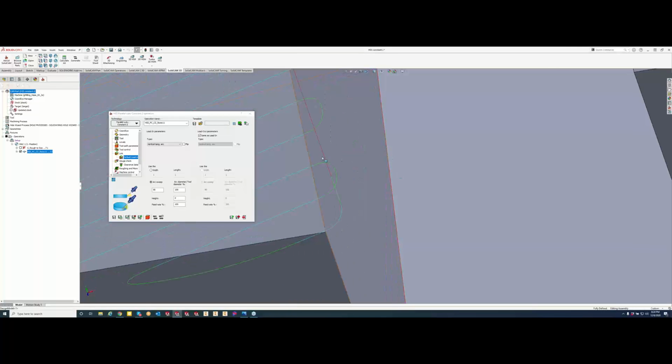So now we're coming in doing a straight drop, doing a nice arc into the material at that point right there. Like I said, this is a great point to come in here and maybe you want that feed rate to be slow as it's arcing into the material. Maybe our stock is a little bit oversized or coming off a saw cut. We might have a plus or minus 25 thou there, so our stock might be a little bit thicker than what we're assuming for. So this is a great way to slow down and then come into the material.